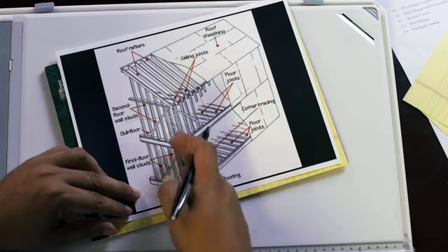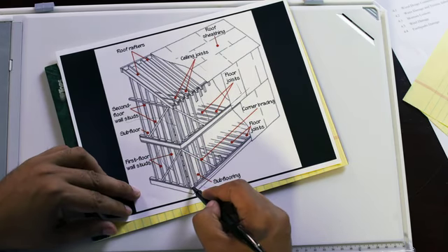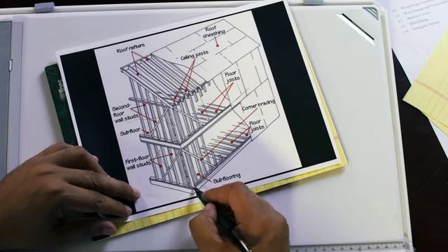And this is important for architects to understand, that you can't design a complete column that's going to span from the base of the foundation all the way up 40 feet. I mean, it's unrealistic. And I've seen designs like that happen, and it's not possible. You have to remember that you have engineering limitations on your materials.